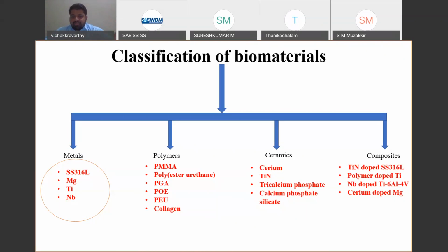To form a composite, for example, an aluminum metal matrix composite, the name itself indicates that aluminum is the main matrix material. So it will be melted to its melting point, and the other reinforcements, like titanium nitride, or if you're adding a small quantity of nickel or titanium, will simply be preheated to around 300 to 450 degrees C and added to form a composite.